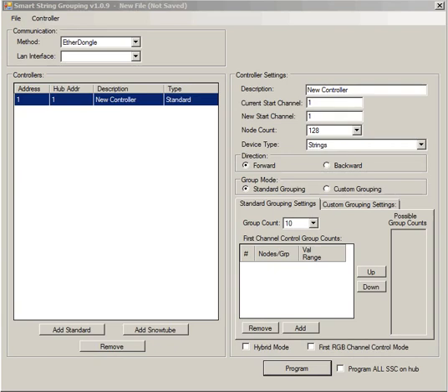If you've taken an SSC version 1 or 2 and converted it to SSC 3, then you'll have the jumper taken off. If you have not done the conversion and you're still running SSC version 1 or 2, then you'll leave the jumper on. If you've done the modification, then you'll take the jumper off. So that's the only purpose for the jumper, so make sure that you have that connected properly.